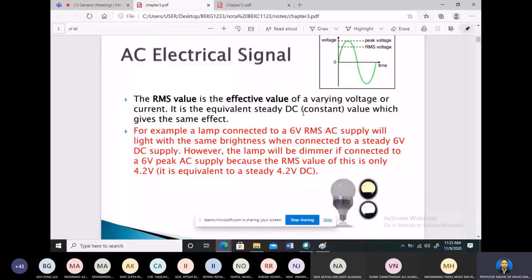And then you have to calculate the voltage peak, which will be maybe 300 something. The given supply is normally the RMS value. If it is not stated in the question or in the books, automatically you have to remember this is the RMS value.